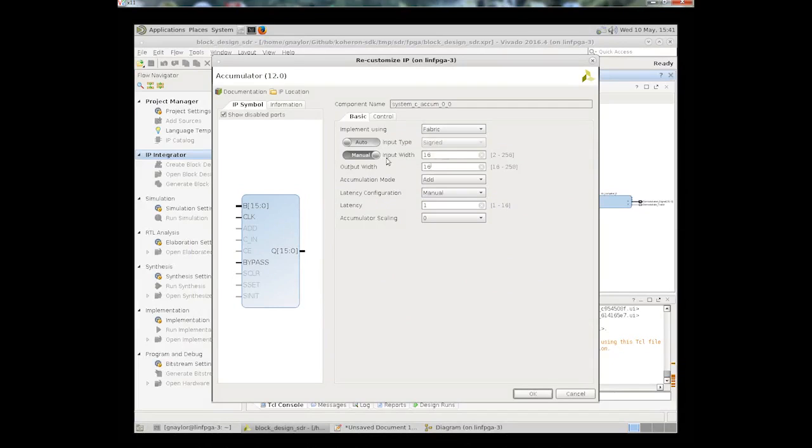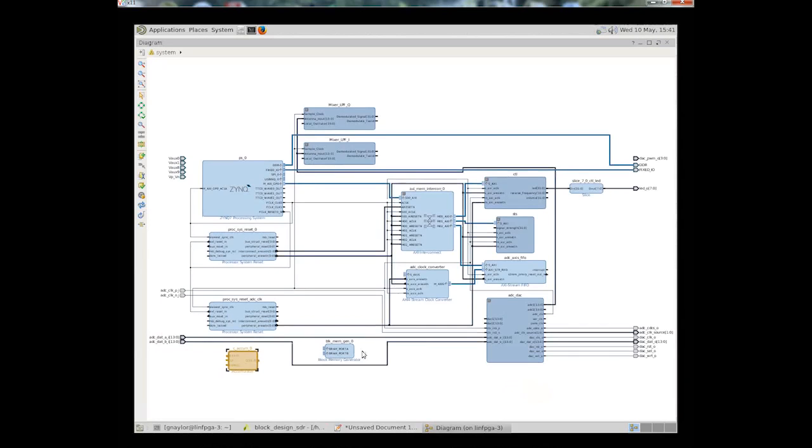We will drive it with a 32-bit value, which we're going to get from the control registers, the set frequency register value. So bring that 32 out, and it's going to mean adding accumulator. And so the input value we will take from this receive frequency here.